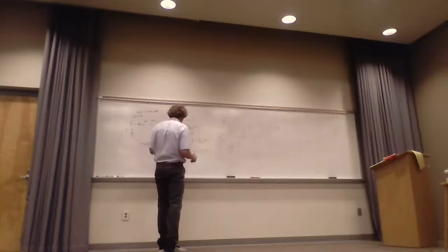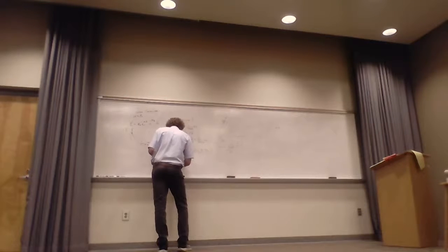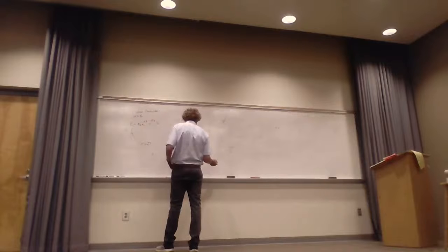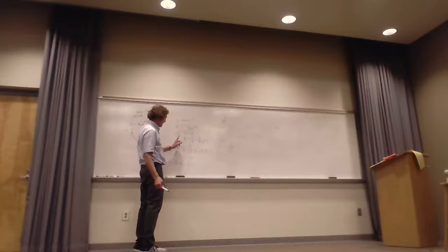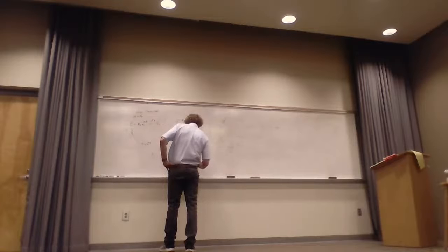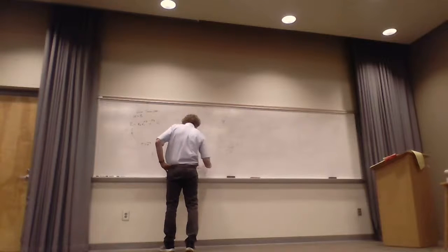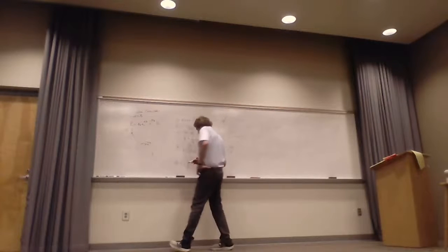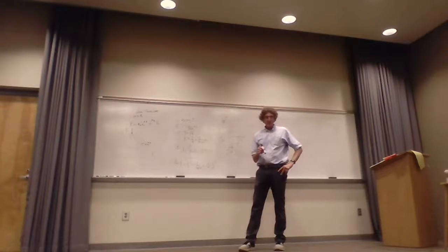So I get this, and then I find the resistance, and that was equal to V over I. And here you can look. When I do this, there's my E, right there. When I multiply it by L, I get an L up here. And if I divide by I, I find out I get L over pi a squared, divided by sigma. Or really, it's equal to 1 over sigma, the ratio of length over area. Now that's the DC resistance. Do y'all remember doing that? Okay.